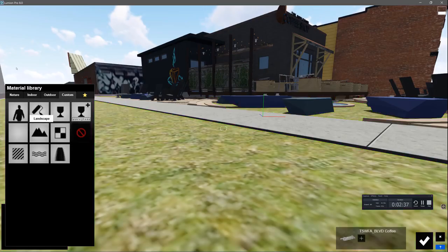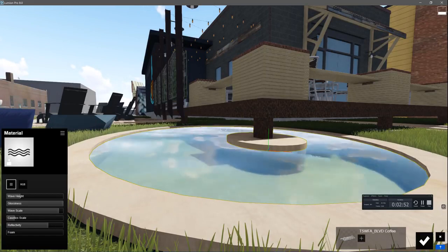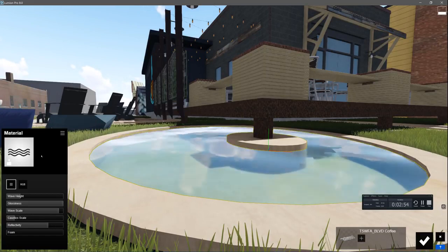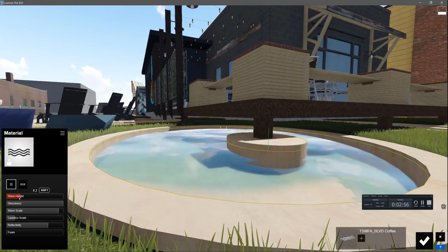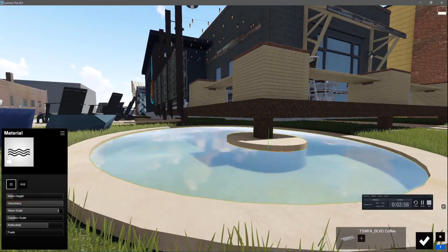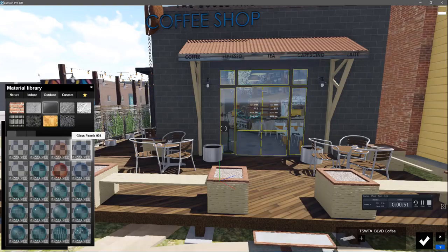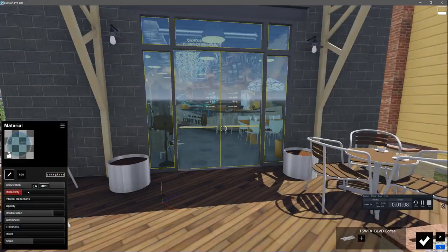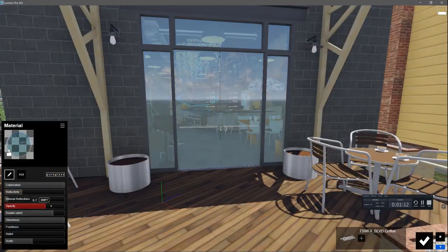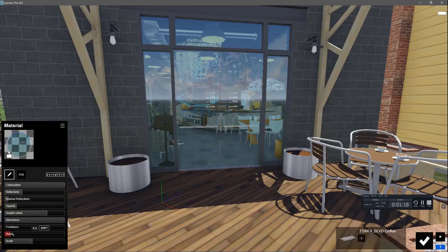Glass, grass, and water are good candidates to be swapped out and replaced by the animated, optimized, realistic Lumion materials. Lumion has trademarked Pure Glass presets available in the Outdoor Materials tab. You can change the specific properties of any glass style that you select. Adjust the sliders to get the look you want. I like a little relief in my glass to take the computer edge off.